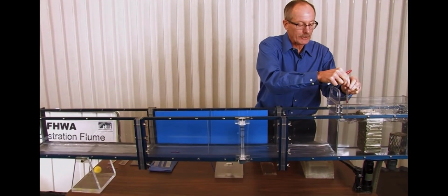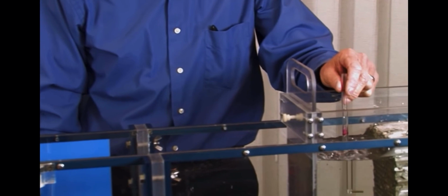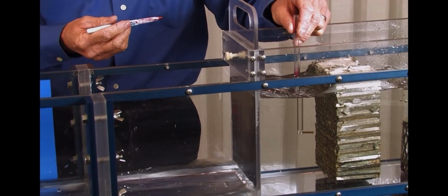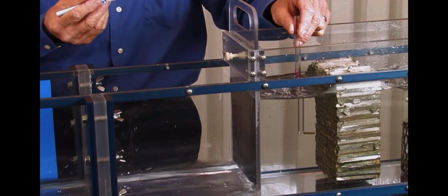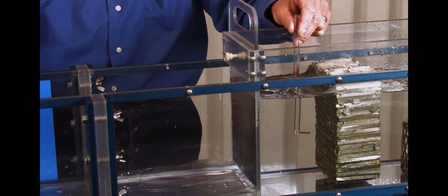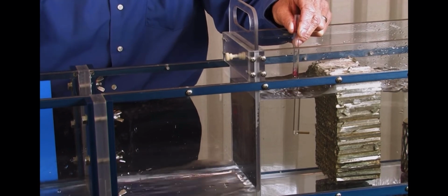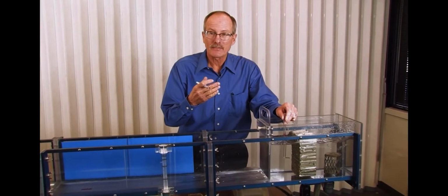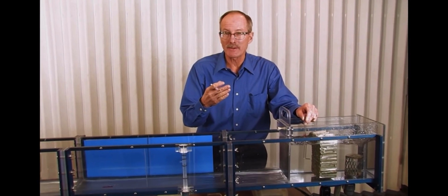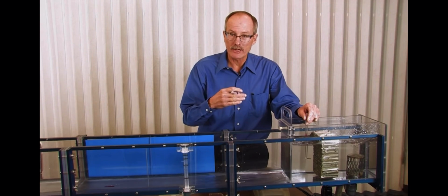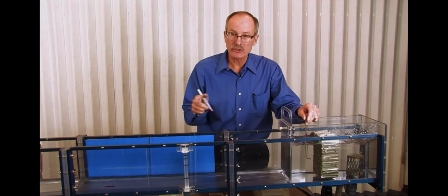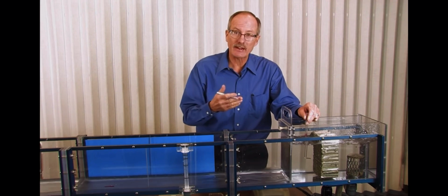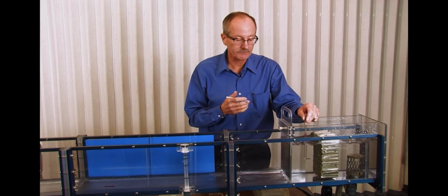So if I measure first the velocity head in the head box, well, there's hardly any rise at all. And that's kind of what we expect, because in a ponded water condition, there's not much velocity. So therefore, the velocity head, v squared over 2g, is very small. That's why sometimes in a ponded water condition, we make the assumption that the hydraulic grade line, which is the energy grade line minus the velocity head, is exactly or nearly exactly the same as the energy grade line.